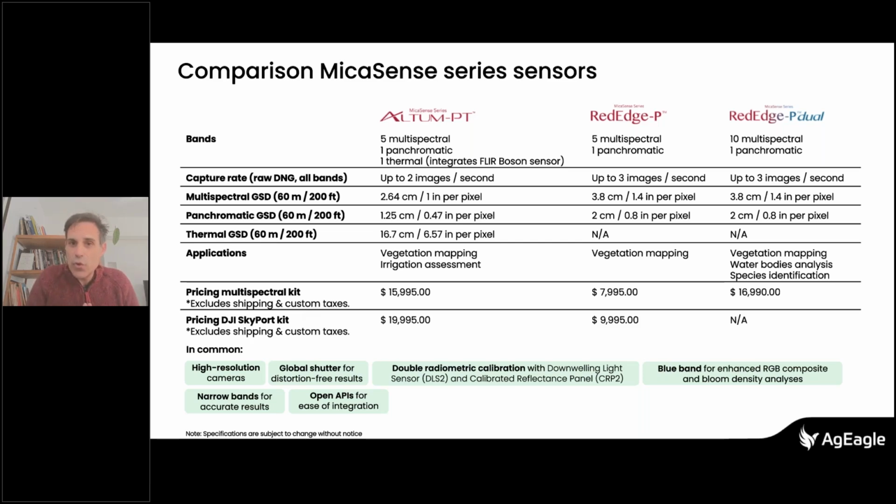That's something you do in either Pix4Dfields, where you have an option, just one tick, to do pansharpening once your orthomosaic is done. It's just one tick that you need to click on. So that's the easy one in Pix4Dfields. Then we have Metashape or Agisoft, however you want to call it, where you also have this option, but usually what you want to do is join them after, right?